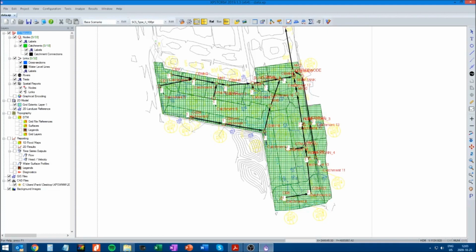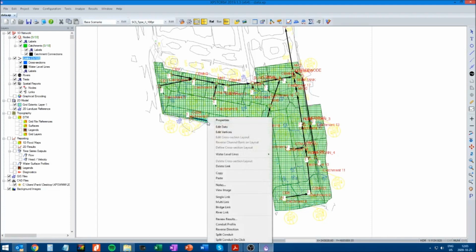So I'm going to set up overflows between the individual catch basins, and I have been provided with the spill elevations. Hopefully they correspond to the top of the ponding elevation. We're going to double check that, but the way I'm going to do it is, if there already is a connection between two catch basins, then we will turn that into a multi-link.